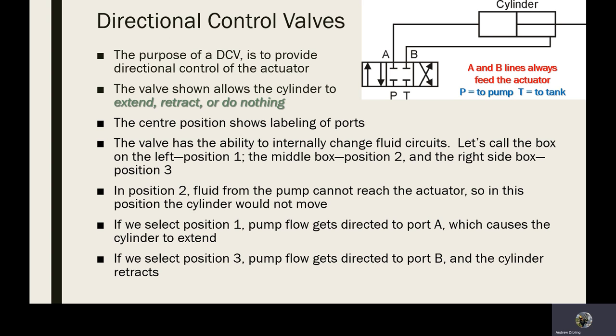A directional control valve. Now, directional control valves can be manually operated, electrically operated, operated by hydraulic pilots. There's many different ways you can use it. Now, they're all very much the same, and I just love the schematics and the logic representations in all of hydraulics because they make sense. P is from the pump. T is going to tank. A is going to the A side of the cylinder. B is to the B side of the cylinder.